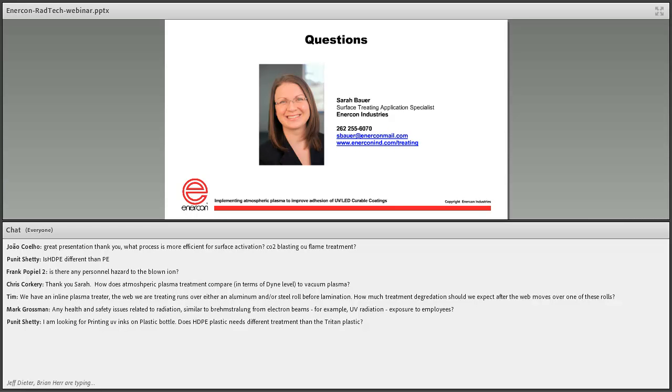So that's actually a very good question. It's going to be very dependent on the material, and I'll give you a couple examples. Flame treatment is a very universal type of technology. It treats quite a variety of plastics. We know it does a great job at cleaning, so metals are a really good substrate for that to work with. Some of the limitations of flame, however, is when we get into rubbers and silicones or very heat-sensitive materials, we know it actually doesn't do a very good job.